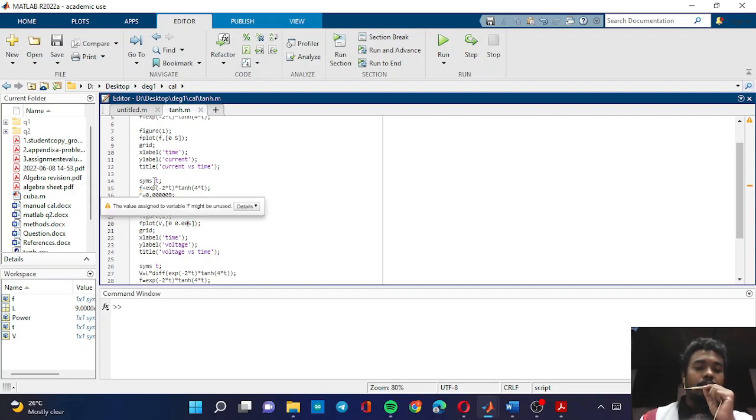This is the coding for the voltage with syms t and the equation of current, and then I define the value of the inductor, 0.00009, which is equal to 9 micro. So in this coding I put L times the differential of the current equation.